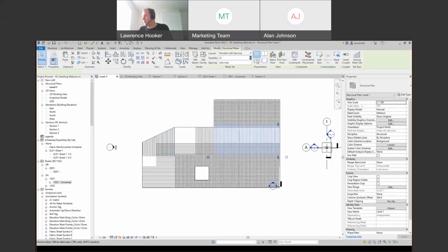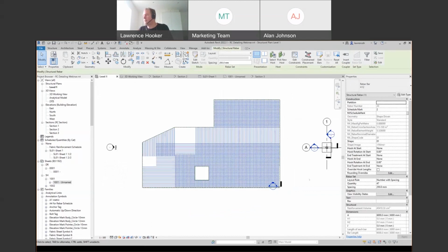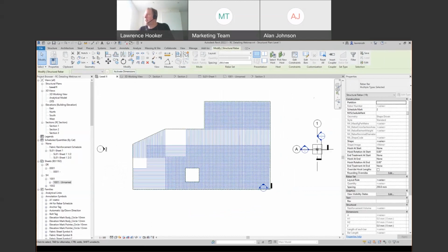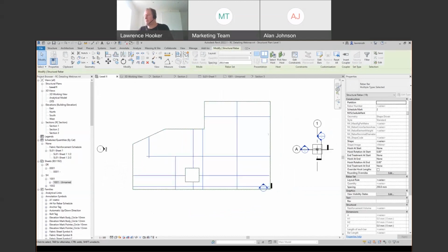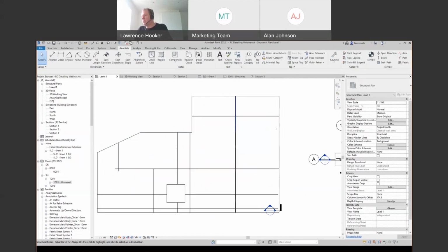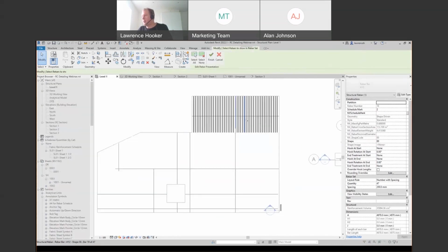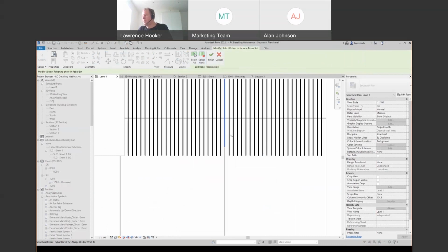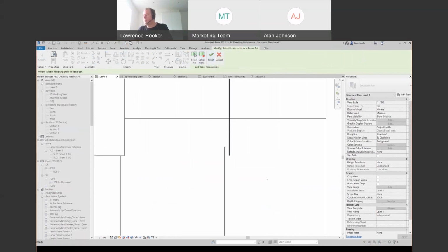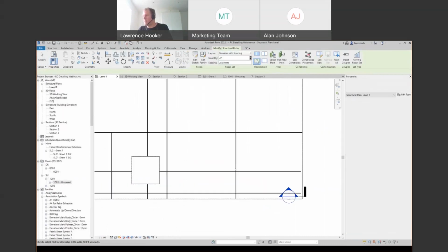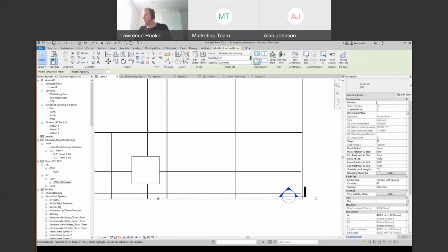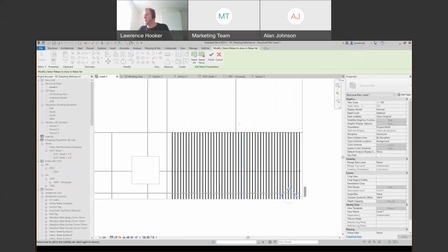select all the rebar in the host, just like you saw me do before over here. What I want to then do is recover the center bar from each of those ranges, just as a starting point. Then I can make some adjustments. Obviously there's a lap there and I want to be able to see that lap. So in here, let me display that bar perhaps. And then if I come down to this range at the bottom, we can select it, go back into our Rebar Presentation, select none, and I want to show perhaps that bar, like that.